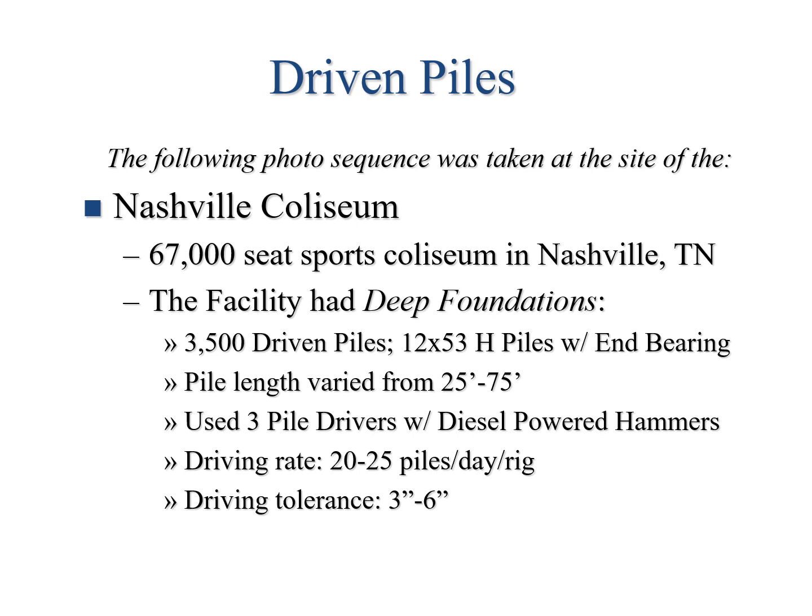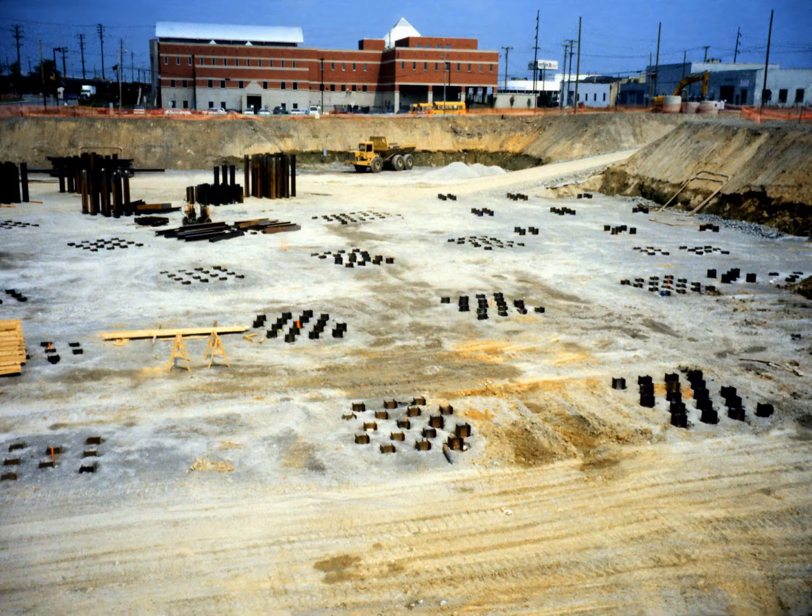So they used 3 pile drivers with diesel-powered hammers. The driving rate was 20 to 25 piles per day per rig, which is a high amount, very quick. And the driving tolerance, meaning missing their mark, was between 3 and 6 inches.